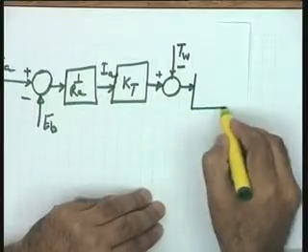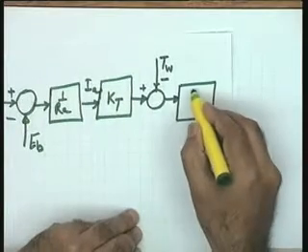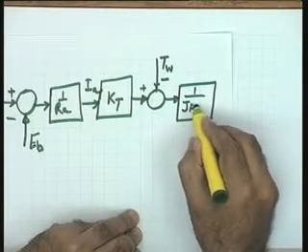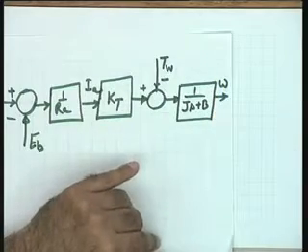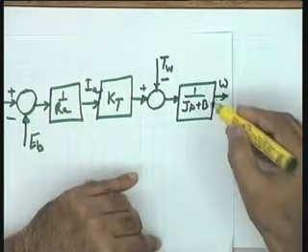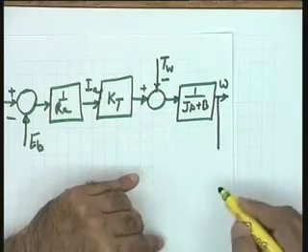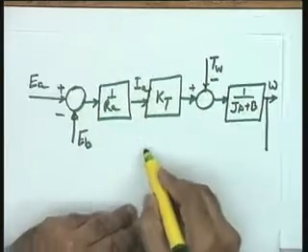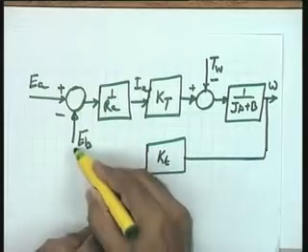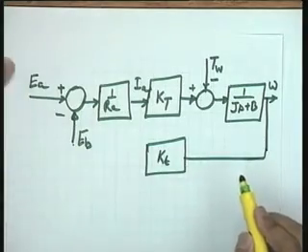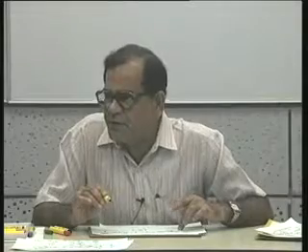And now this torque, since this is driving the inertia, this particular block could be 1 over Js plus B with output as omega. You can see the basic relationships. This omega now can be picked up by the sensor, and here is your sensor transfer function, and this is, I am sorry, there is no sensor here. This is the transfer function of a motor only in the open loop mode. There is no sensor as far as the motor is concerned.